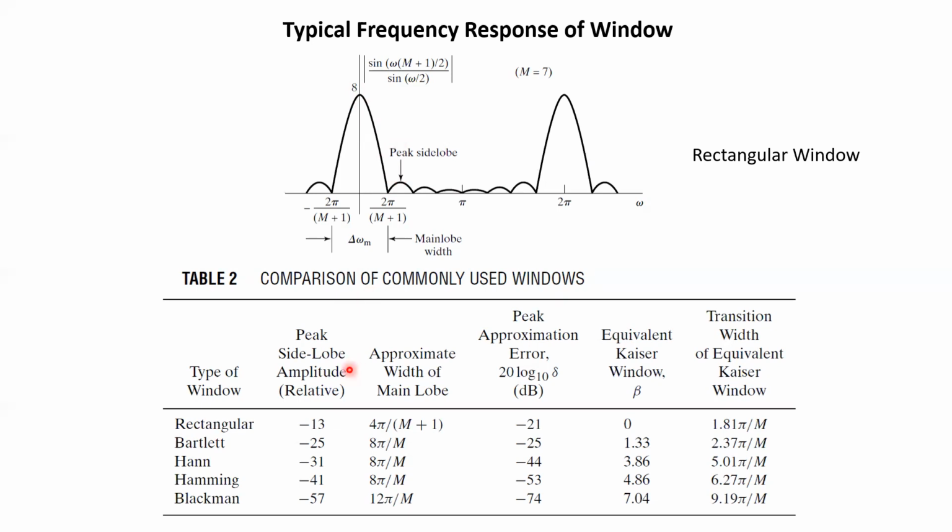Normally this is given in dB, okay, so we have to calculate this value in dB, right? Here it is shown as an absolute value, but we have to calculate this magnitude in dB, so we also have to take 20 log 10, and then give this relative magnitude.